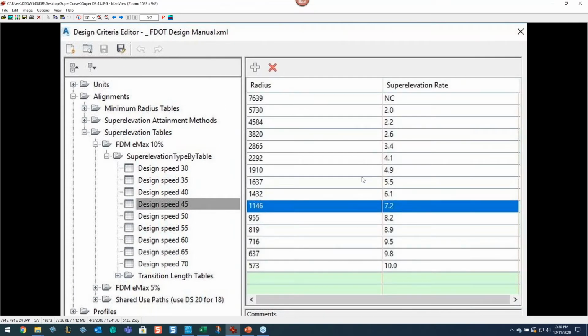You can look at the DOT manual or the DOT criteria or the design manual, et cetera. That's fine, if you know. But for me, it's much easier. This table comes from Civil 3D. This comes from the design manual. And if you look, it's looking at this category, and just looking at the radius you have here, you can basically tell what your superelevation should be. Yes, you can do the math if you want to, but this is going to be close enough for doing design.